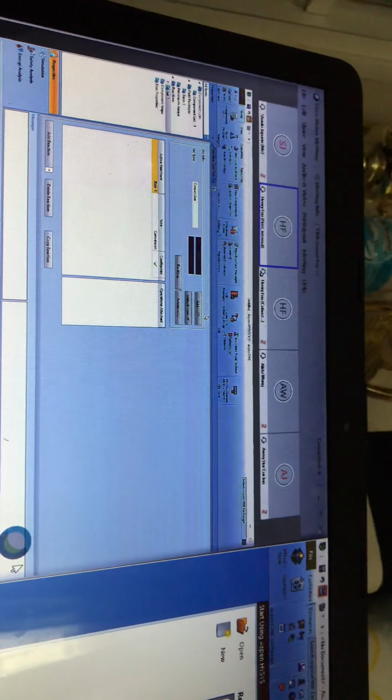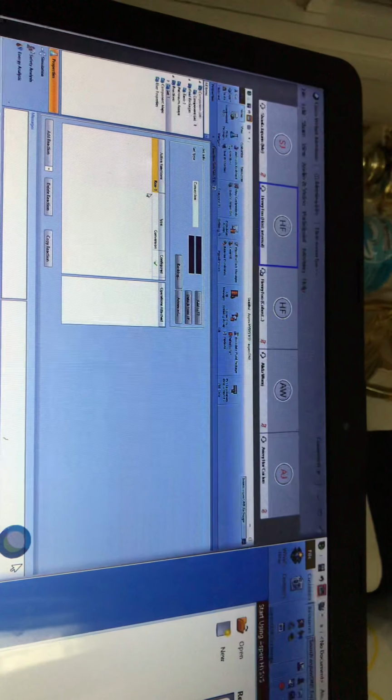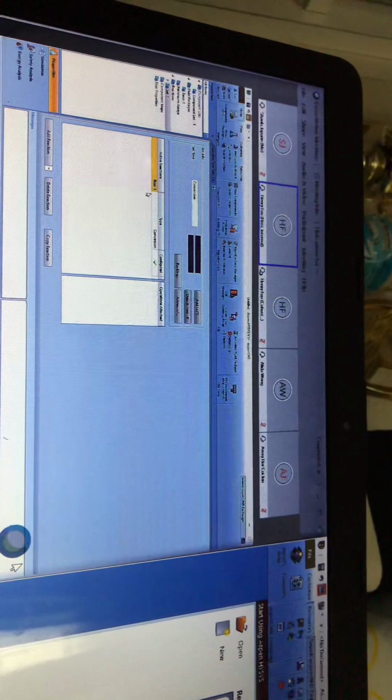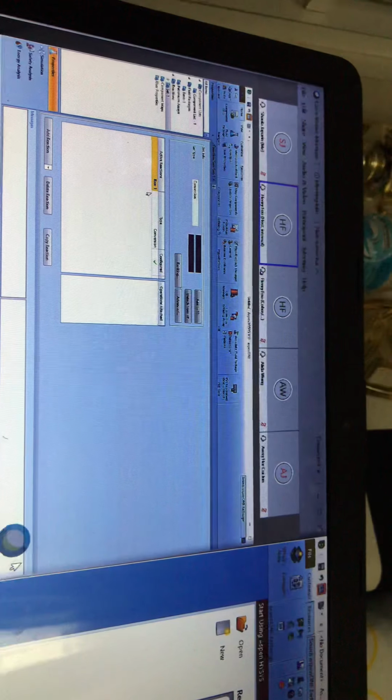So make sure you do that whenever you're defining reactions. Of course, you can define more than one reaction here. You can add new reactions, reaction 2, reaction 3, 4, and 5, or even more. Then you can attach them to different fluid packages, which means you can calculate the reactions based on different equations of state.